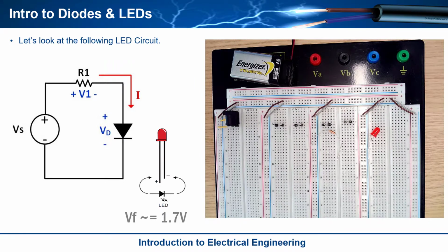And what I want to do now is build this circuit that has a DC voltage source and a series combination of a resistor and a diode. I want to build this on a breadboard, and do some calculations on what I expect to see in terms of the voltage across the resistor, extract what I think I'm going to see in terms of voltage across the diode, and then do calculations using the constant voltage drop model and figure out what the current's going to be. So I want to basically calculate and verify by measurement.